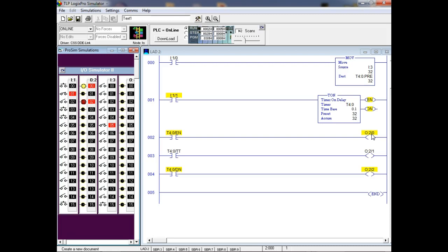Mask bit means if I'm using some of my push buttons to control a circuit, and then I'm bringing in a number on, let's say I'm using 2 of them to control the circuit, and then I want to use the other 6 for variables, then we have a way of doing that. We have a way of stripping off what we don't want. We call them masks. And we'll learn how to do that in this class too.